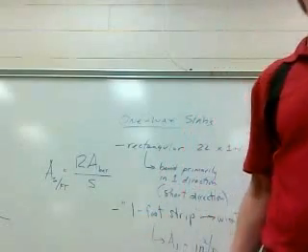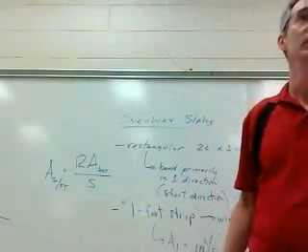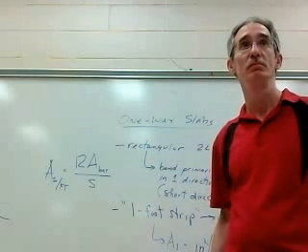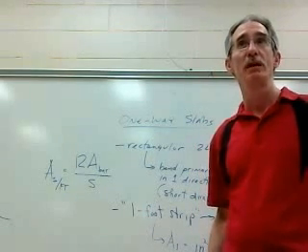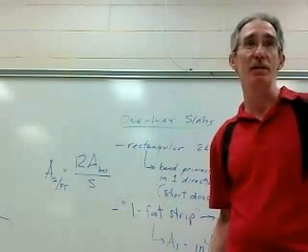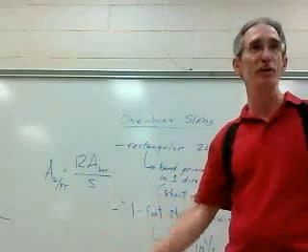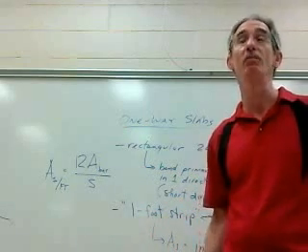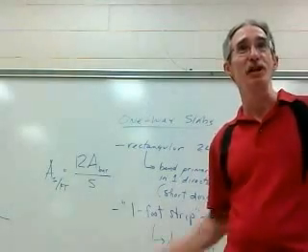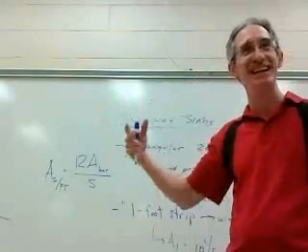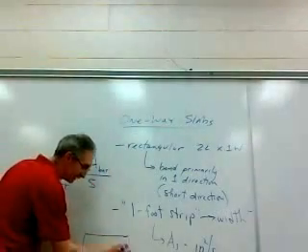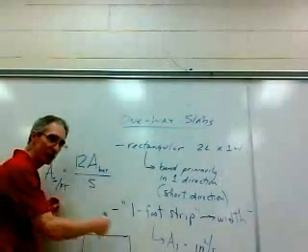Yes. You take the 1 foot strip, wouldn't the moment be more in the middle than at the end? Yeah, we're going to consider them to be simply supported. It depends, but usually floor loadings are going to be uniform. If that's my slab, it's supported on all the edges.